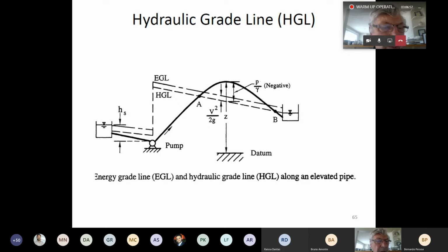And you'll see when we go down to, well, the reason for that is because when the pressure in the fluid drops below the vapor pressure, the liquid starts to boil. And that's a condition called cavitation. Or it could also be something called slack flow. And you'll see that in the next slide. But where you get this two-phase flow, it's more likely to happen near the summit of a mountain, at a very high point on your pipeline system. And it can do very serious damage to the interior of the pipe. It can even make the pipe collapse, actually. So we'll talk a little bit about what we do to mitigate that in the next slide.